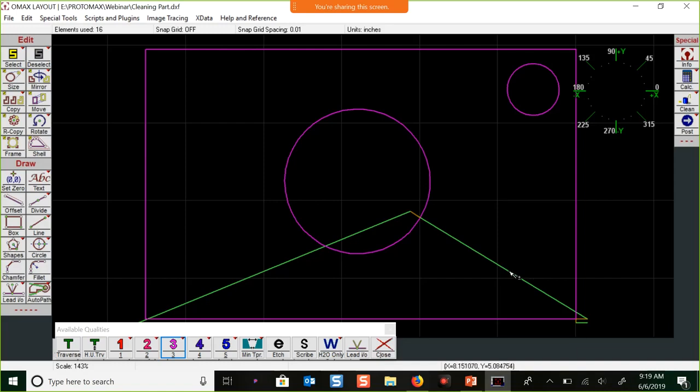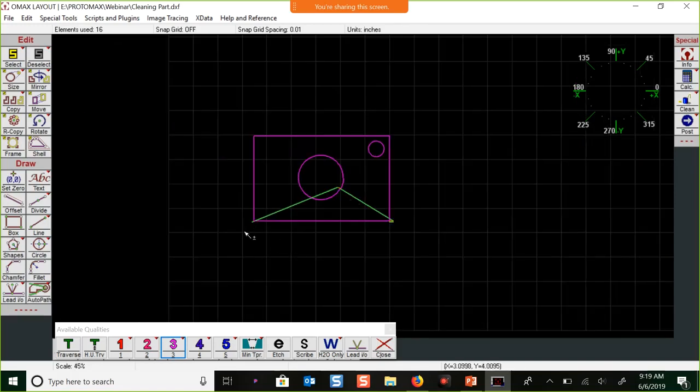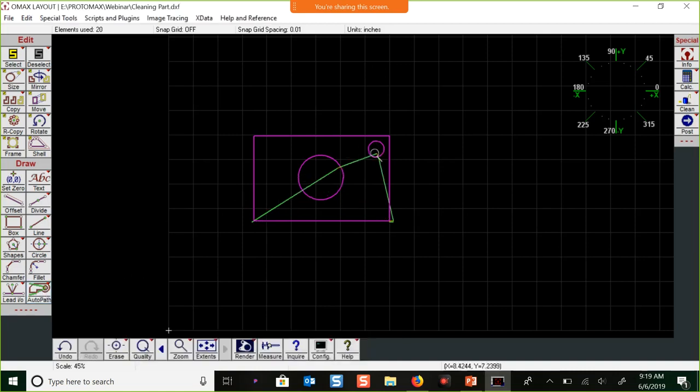The only way to really do this, to align it up to cut a pre-existing part, is to make sure your nozzle is set. A lot of people start at the bottom left corner of the machine, then they put the material in, so you can do some math to determine where this particular part is aligned to where you need to start cutting to cut another circle. But you simply add whatever components you need into the drawing, repath it, resave it, and you've got new features within your drawing. Does that answer your question?